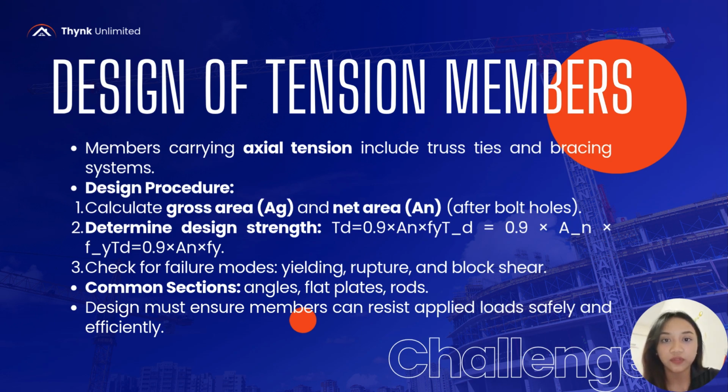Third one is to check for failure modes: yielding, rupture, and block shear. Common sections are angles, flat plates, and rods. Design must ensure members can resist applied load safely and efficiently.